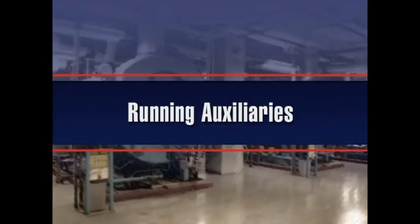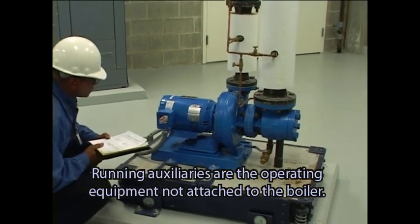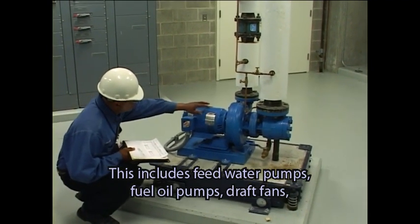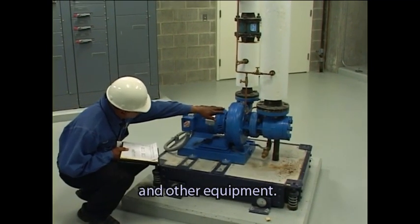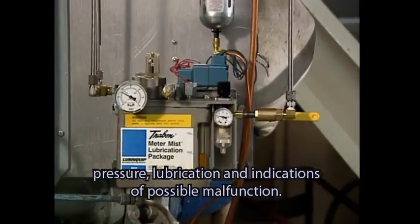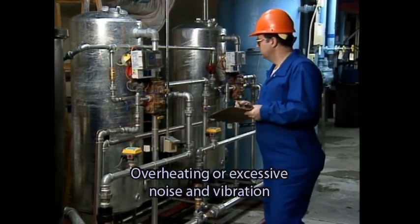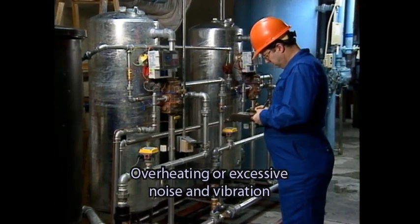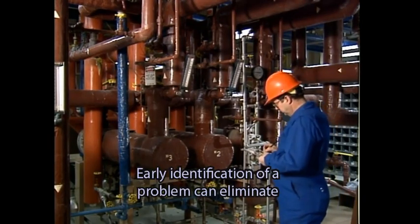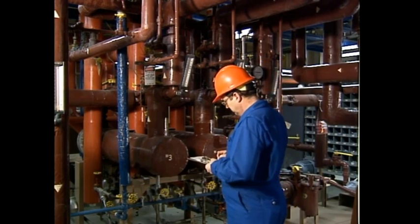Running auxiliaries. Running auxiliaries are the operating equipment not attached to the boiler. This includes feed water pumps, fuel oil pumps, draft fans, and other equipment. Running auxiliaries must be checked for proper temperature, pressure, lubrication, and indications of possible malfunction. Overheating or excessive noise and vibration are indications of a potential problem. Early identification of a problem can eliminate or reduce equipment damage and repair costs.